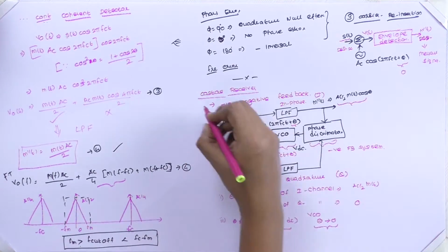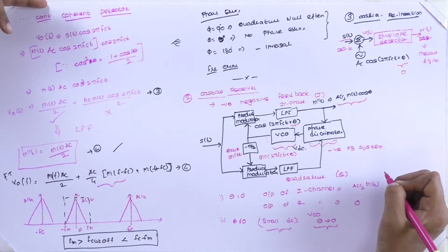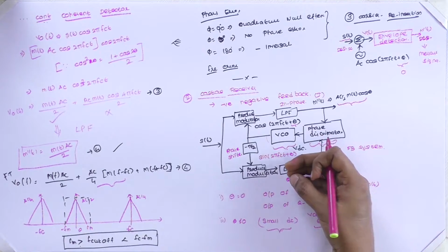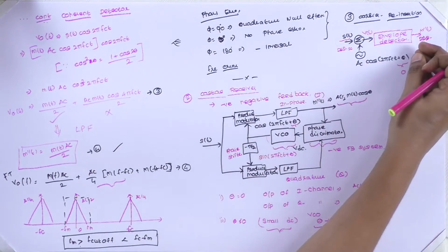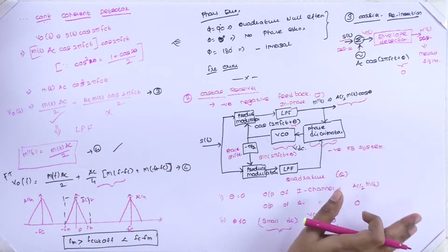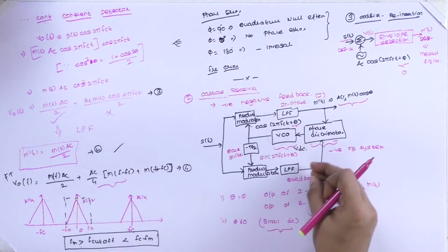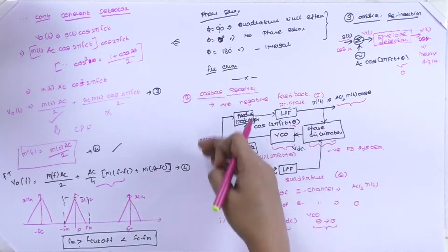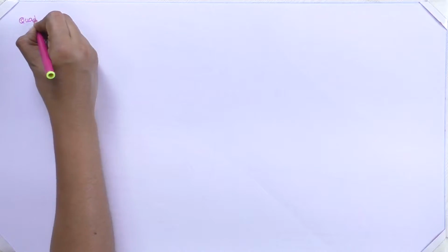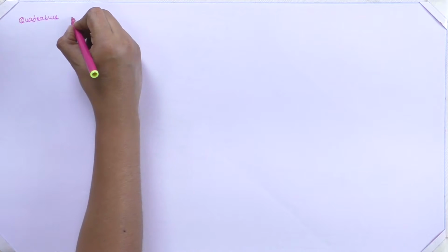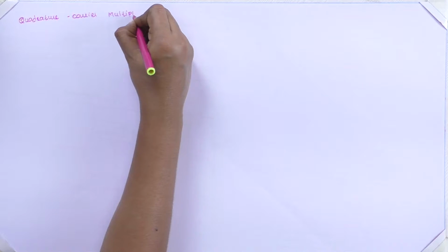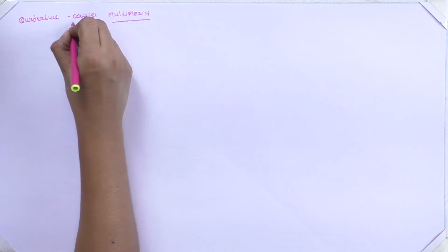So we have seen the balanced modulator on the demodulation side, the Costas receiver, which applies the negative feedback system, and the carrier reinsertion technique using the envelope detector. We have seen the three demodulation techniques. We are now going to see one application using a slight modification of the Costas receiver with the negative feedback system: how we can simultaneously pass two message signals, called quadrature carrier multiplexing. This is one application of double sideband suppressed carrier.